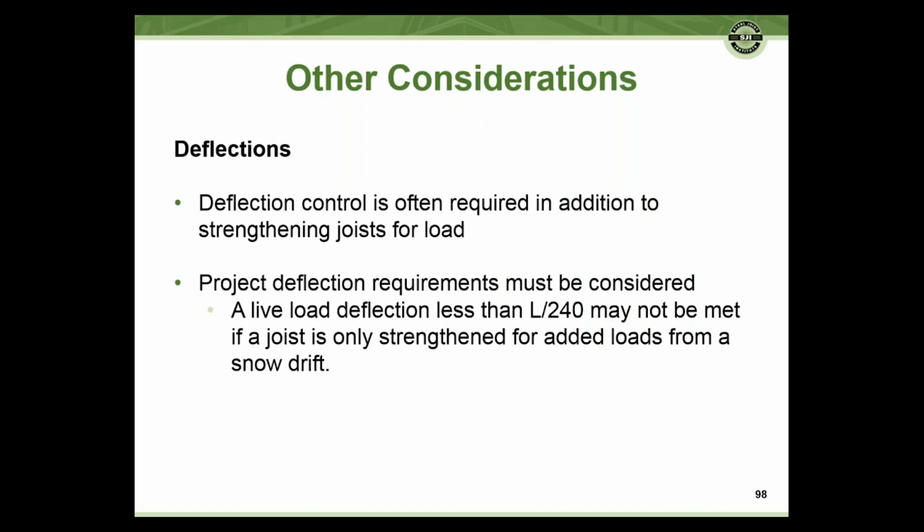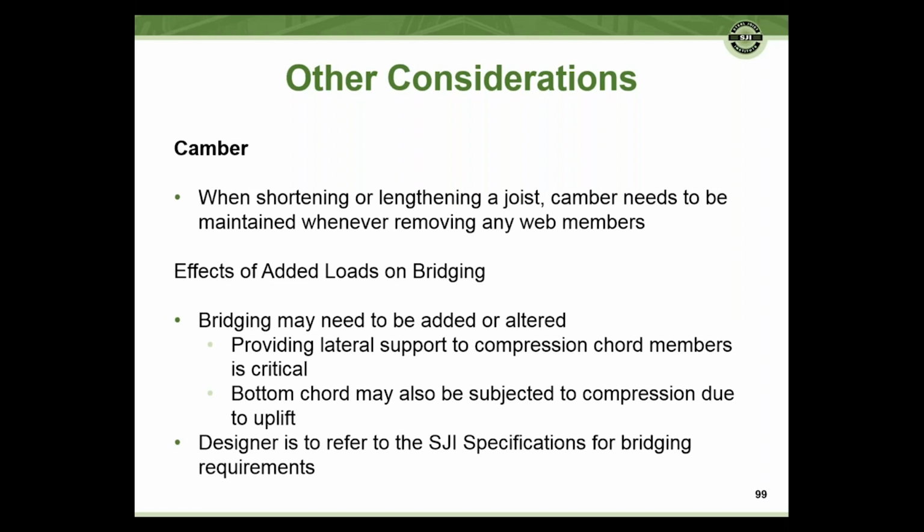Deflection can control. Also make sure to check your live load deflection because deflection requirements could affect strengthening or adding loads to a joist, especially if you've got any added snow drifts if you're lengthening a joist. So be very careful that deflections don't control that. When shortening or lengthening, as I mentioned, camber, you need to try to maintain that camber. When you start removing webs to do either lengthening or shortening, you can take some of that camber out.